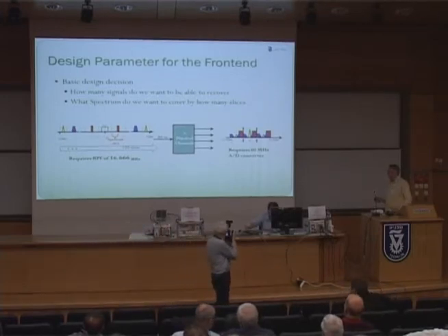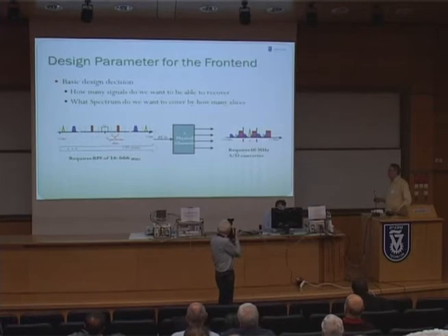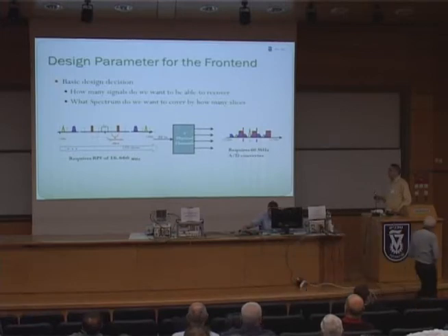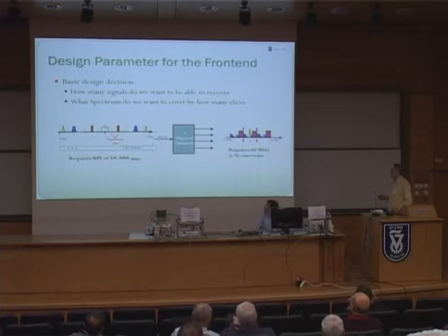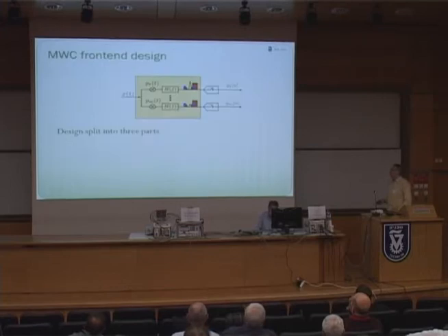This would limit us to a very small number of signals we can detect. Bora showed this: we have the possibility to have a lot of information in one channel, or a lot of channels with one small piece of information. We decided to have 3 slices combined into each channel. This gives us 60 megahertz for our A2D converter.